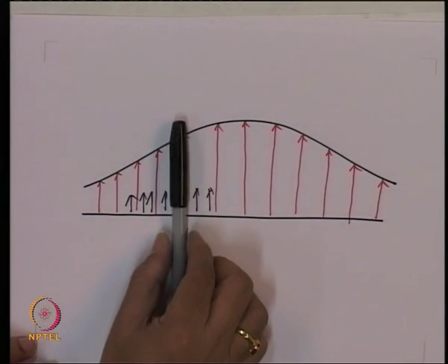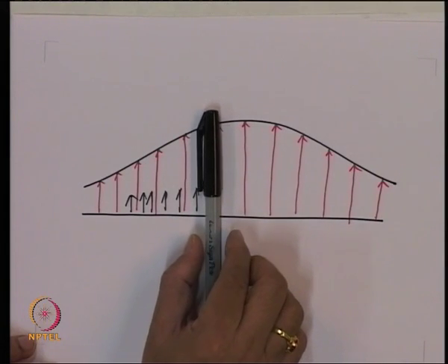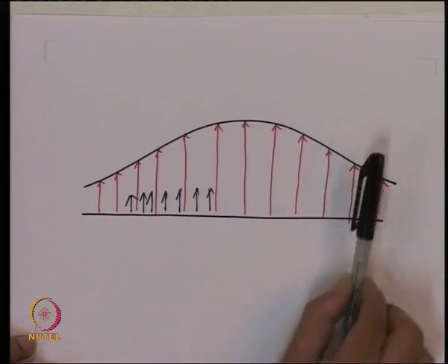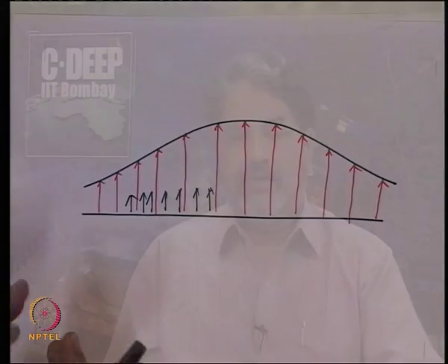So, essentially what we are saying is that the pulse which rides on this carrier travels with a certain speed, the pulse which rides on this travels with a different speed, this with a different speed, and so on. And because of this different speed, the pulses riding on different carriers reach at different times, or they take different times to propagate a given length of fiber. And that's what essentially gives rise to what is called the material dispersion or intramodal dispersion.